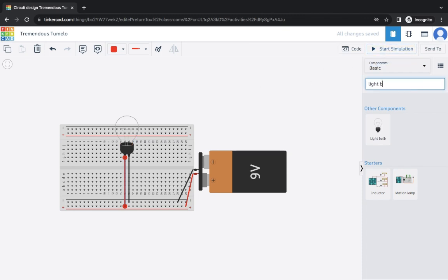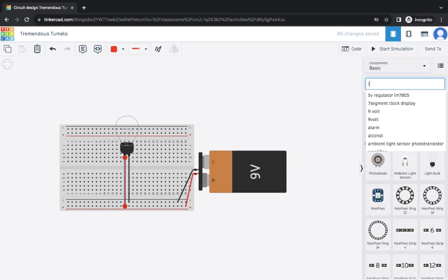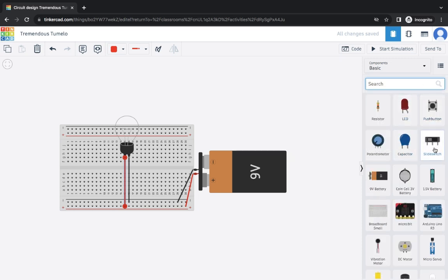Now I want to use an interrupter or switch. So the easiest one is this slide switch. As you can see, it has 3 pins. Terminal 1, common is in the middle, and terminal 2. Remember what I told everybody. The common pin has to be used always. It can be positive, negative, location doesn't matter, but you have to use the middle pin called common. So I'm going to use this one for a positive row.